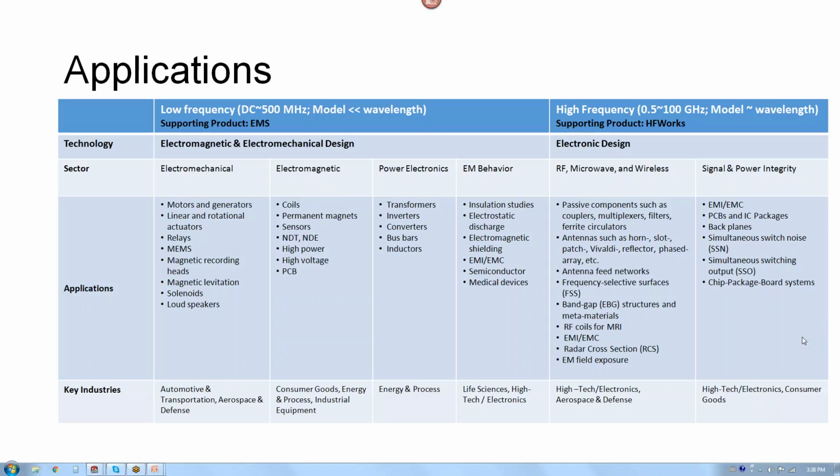There is also a question about induction heating. Yes, do we do induction heating? Absolutely. I can model a coil and pass current through it at a particular frequency and use it to compute what is the heat generated. You can use it as an induction heater basically, and we have some examples highlighting induction heating in our trial version. You can find out the induced current on the workpiece, and even one step further, you can set up a thermal simulation to find out the temperature distribution on your workpiece. So if you have a model of induction heating, we will be able to handle that application.